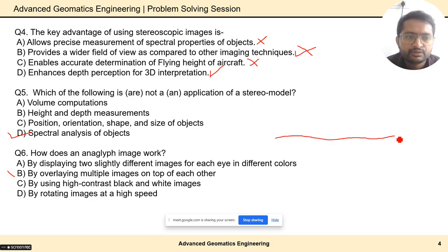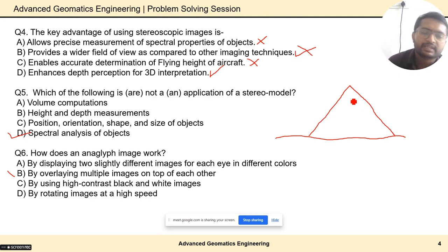So how do they generally use this on site? They have some material stacked up on site, in this kind of bump, where the construction material is stacked. It may be sand, soil, or gravel or anything. So what they will do, they will find out the height of it. They know the base level, and they know the shape of it, whether it's a circular one or some other shape, and then they will find the corresponding volume. So they will be able to see how much volume of any particular material is available on site. So option D is the only correct answer.